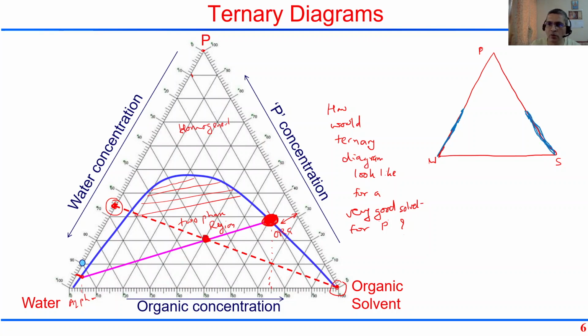the organic phase, there is no solvent going in the aqueous phase, and this two-phase region should be as wide as possible. So it is as if you would want the two-phase region to be equal to the whole triangle itself. Now, if your tie lines are like this, then you can say that practically no organic solvent is there in the water phase and practically no water is there in the organic phase, right? Obviously, this doesn't happen when you go to larger and larger concentrations of P.